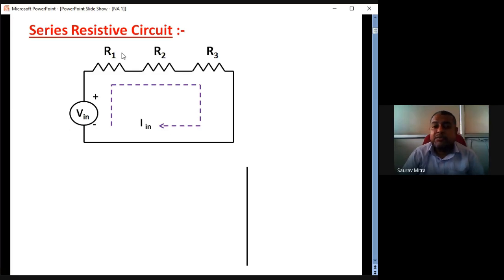Okay. In the kilo ohm range, it can be a 1 kilo ohm resistance. There is a 1.2 kilo ohm resistance. There is a 2.2 kilo ohm resistance. There is a 1.8 kilo ohm resistance. There is a 3.3 kilo ohm resistance, 4.7 kilo ohm resistance, 5.6 kilo ohm resistance. So there are certain standard values of resistances. Okay. So whenever you are choosing R1, R2, R3, you can choose from 3-4 different ranges, and you can do this experiment.